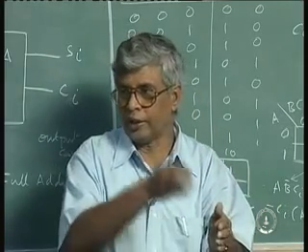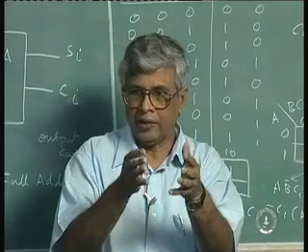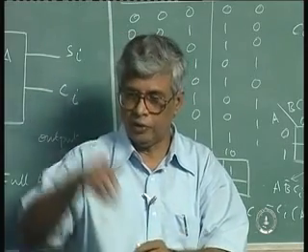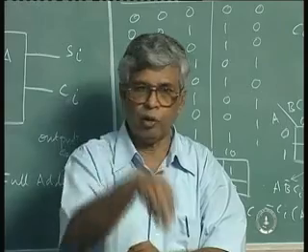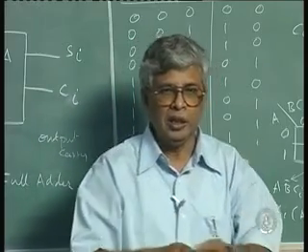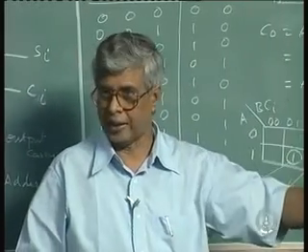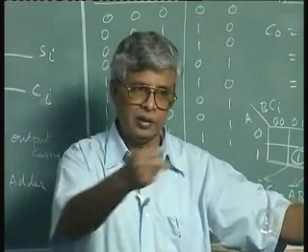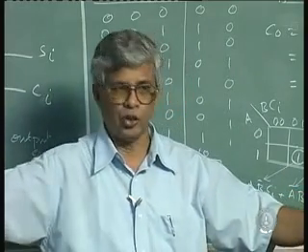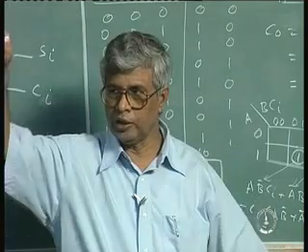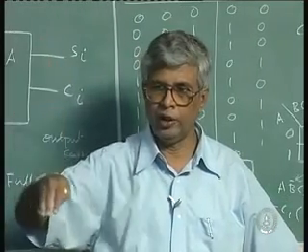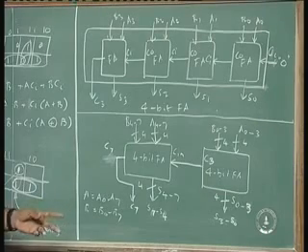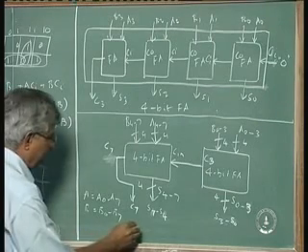First 4 bits feeding to the second 4-bit, carry of the second 4-bit feeding to the carry in of the third 4-bit, etc. Each of these will give you a 4-bit sum, 4-bit sum, 4-bit sum. The last carry would also be considered. Intermediate carries will feed into the next stage, and the very first carry in is 0. And the A's and B's are fed into each of these blocks as is shown here. This is a multi-bit adder, an 8-bit full adder.